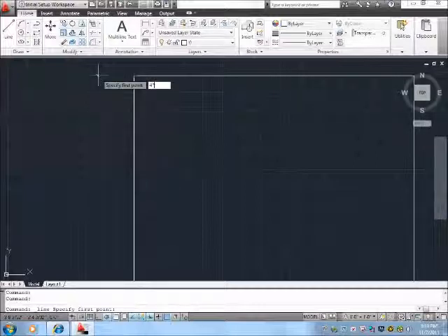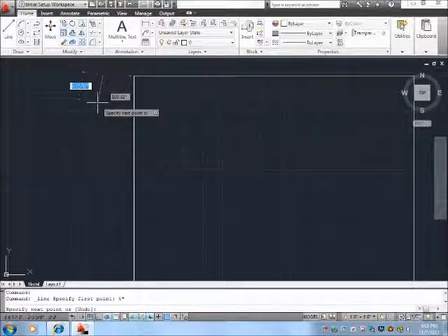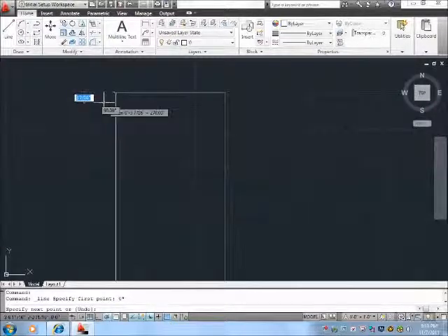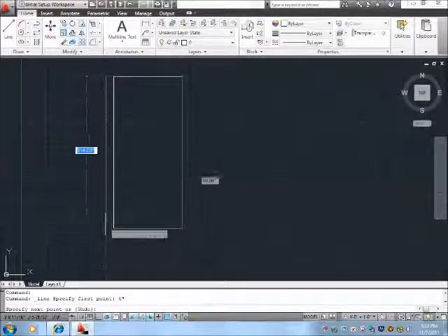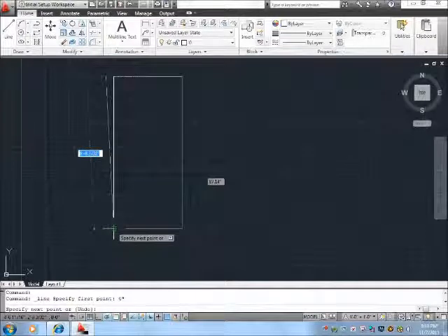as I started. So I'm coming out 4 inches, and so I'm typing in 4 inches away from that point. That was where I used the cursor as a guide. So I'm coming out 4 inches from that point, and I hit enter. And so now that's 4 inches away from the top edge of my door, and I come down until I meet the bottom edge. I use my cursor and go over until I see the green square, and I draw it out.